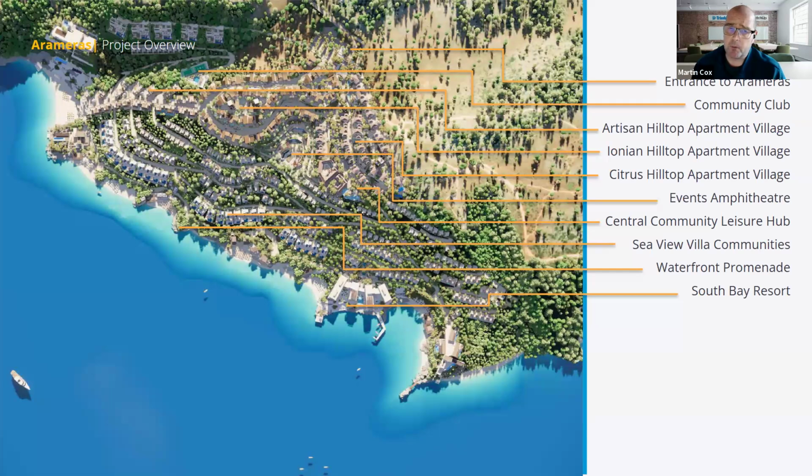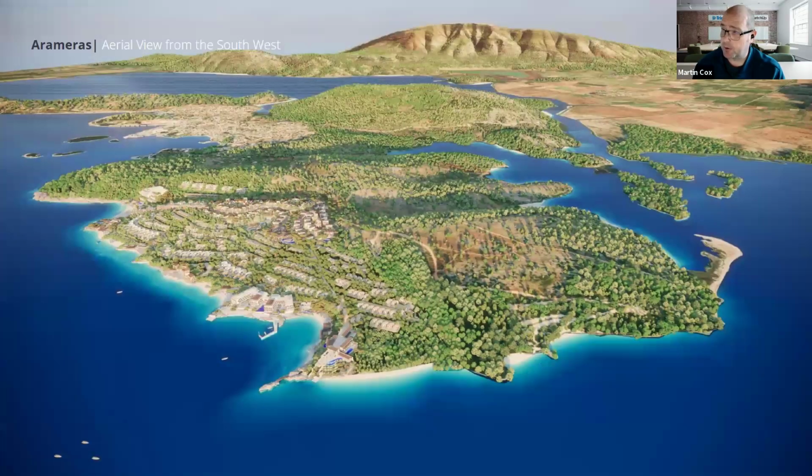Within SketchUp, they were able to use the terrain modeling tools, some of the point cloud information, and also bring in Add Location to set this up in a model of quite a considerable size, because what was quite important in this particular project were the views from the island. They needed to see what other islands you could see, what other views you had.